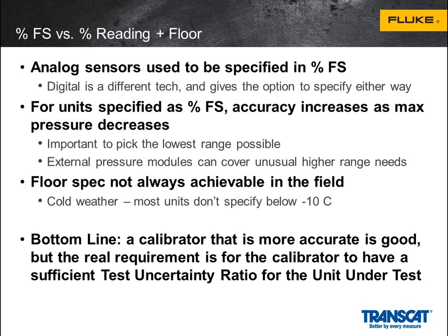So what's the disadvantage of percent reading plus floor? Well, the bottom line is that the percent floor spec is not always achievable. There are many things that can influence the total error that you actually see. And so even though it would appear that the unit is very accurate, it's very easy to get outside of either the operating conditions, or perhaps you have a leak and there are other problems, and you can't achieve that